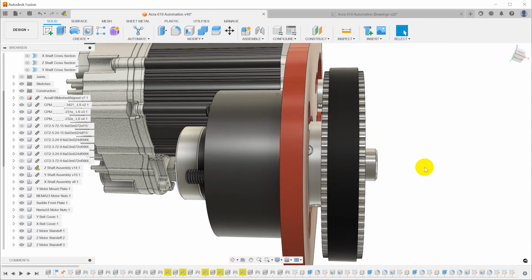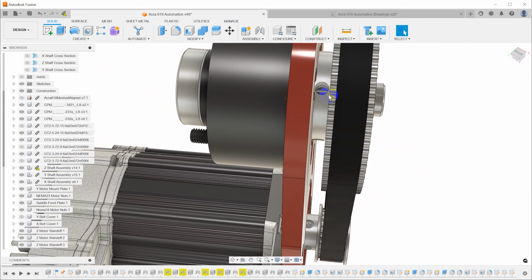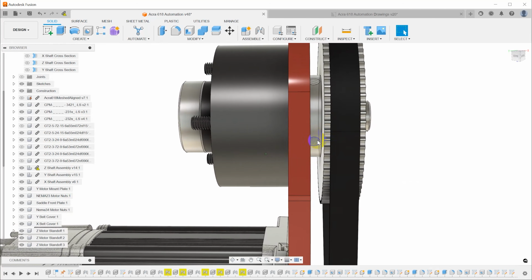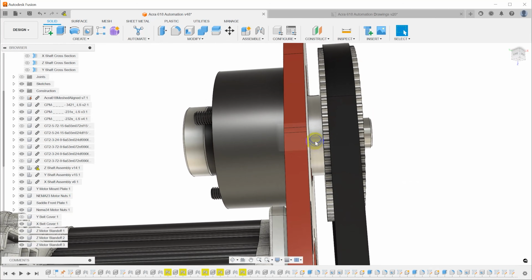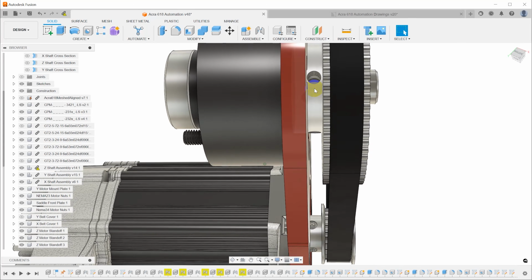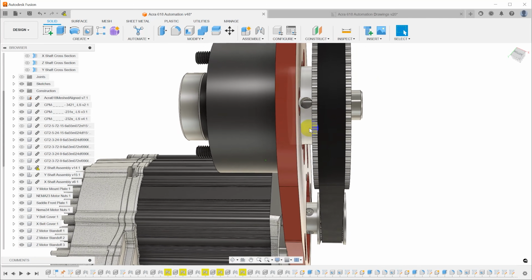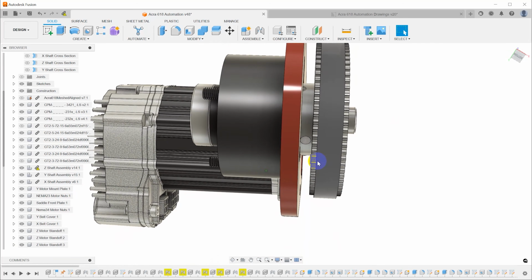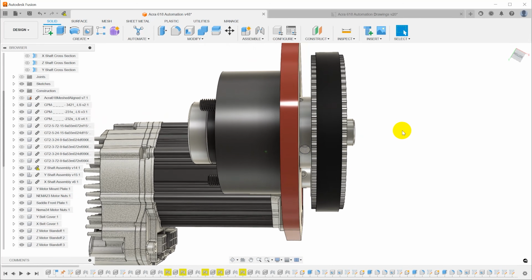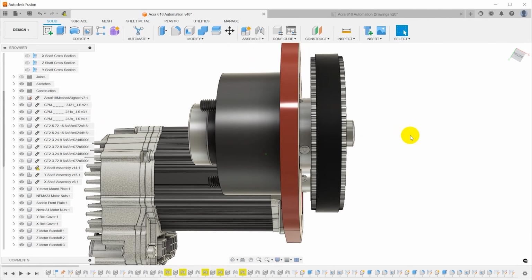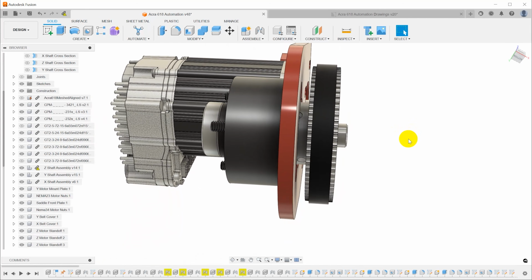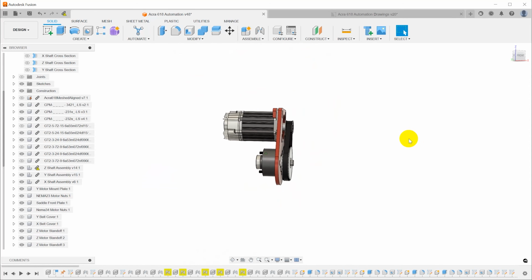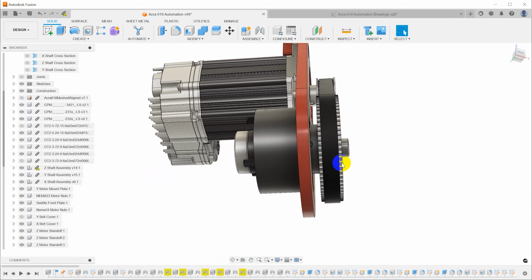So what I need to do is add 2 more set screw holes to the pulley that are as close as I can get them to the pulley face, so that I can get in between this plate and the pulley with a wrench. So that's an M5 screw, and based on all the math that I've done and looking at these diagrams and looking at the model, I think I can get the wrench in there. I think it's going to be a lot tighter on the machine than it looks on the CAD model because, you know, keep in mind, we're zoomed way in on the CAD model. But I think that's going to work.